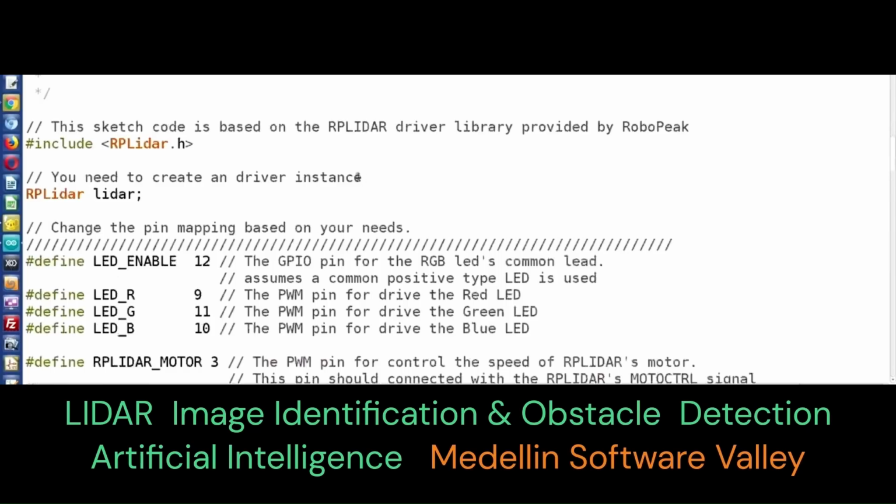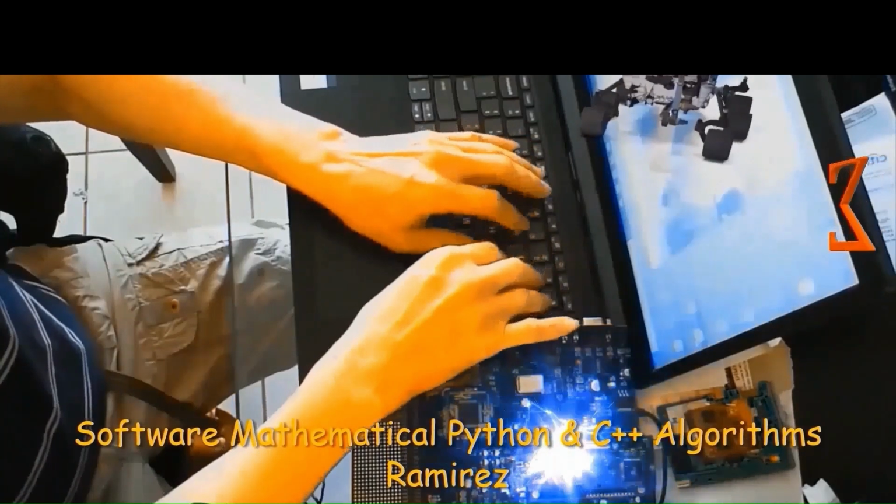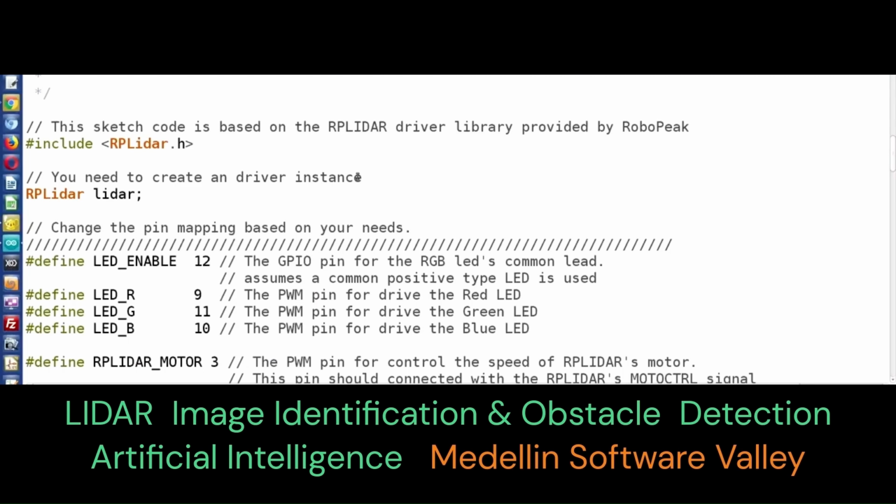In the LIDAR architecture, in the transmitter, the pulse is generated and amplified by the laser driver. The resultant laser beam is then transmitted through the optics.